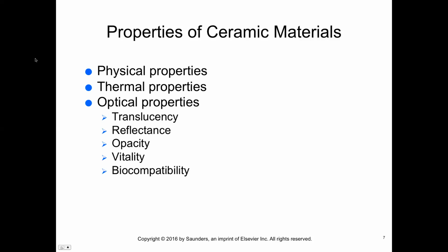Ceramic materials are stiff and brittle, and these properties contributed to the fracture of weak feldspathic porcelains in early clinical applications. Even though ceramic materials are generally stronger when compressed forces are applied, it's their flexural strength that is more important for resisting fracture. Glass-based ceramics have a relatively low flexural strength. Lithium disilicates have the highest flexural strength of these glass-based materials.